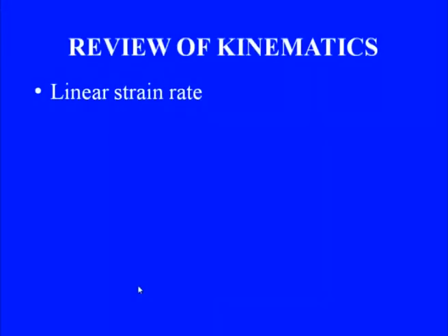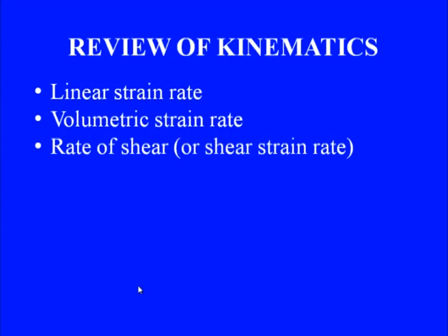We will have a look at how we define linear strain rate, volumetric strain rate, and rate of shear. Now before we proceed to the definition of these terms, let us have a look at one particular derivative which is referred to as material derivative. How do we define a material derivative and what do we mean by it? Material derivative is useful in fluid mechanics in the context of what we call Eulerian description of a flow.